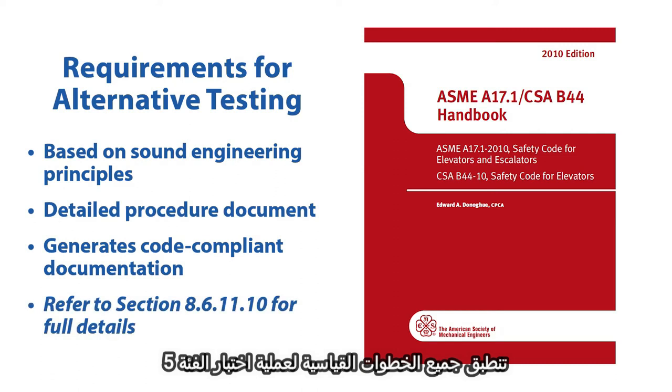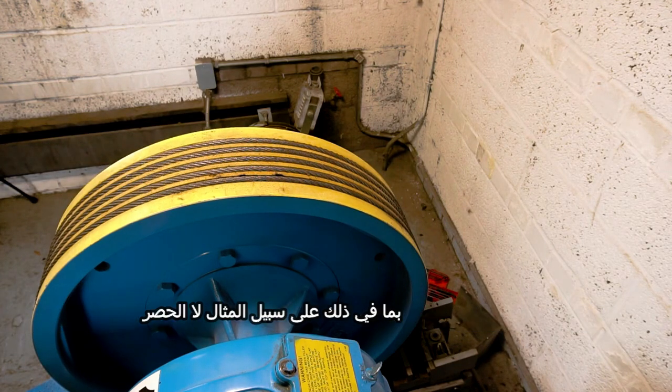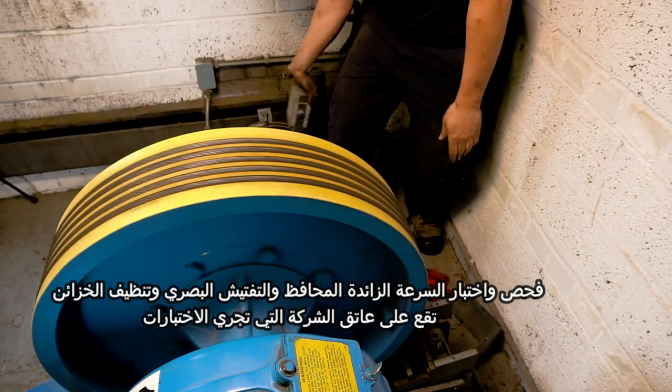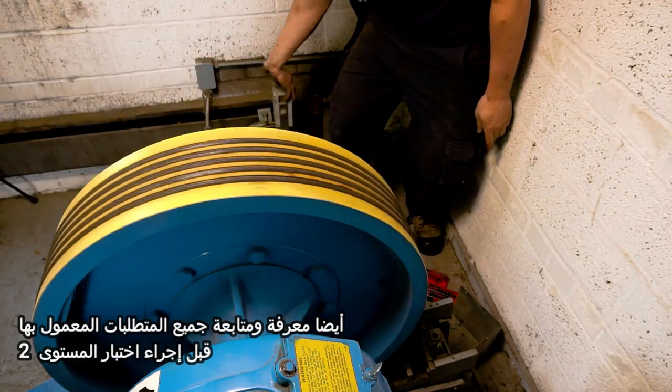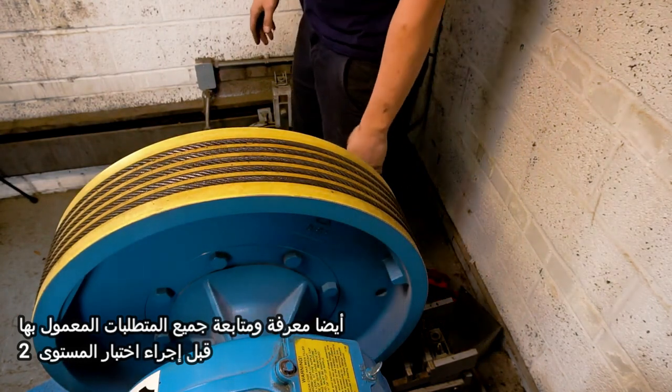8.6.11.10. All of the standard steps of the Category 5 testing process apply. The elevator service company must complete all required checks not covered by the LV2 system, including, but not limited to, inspection and testing of the overspeed governor and visual inspection and cleaning of safeties. It is the responsibility of the company performing the tests to know and follow all applicable requirements.